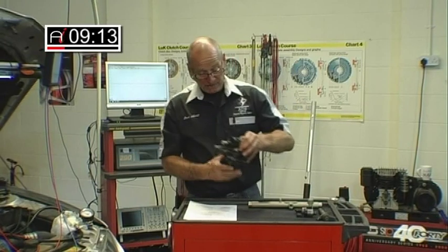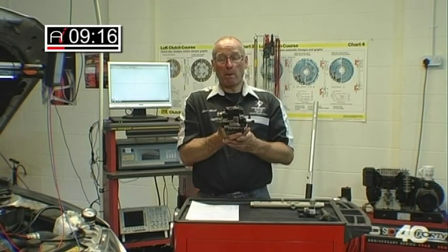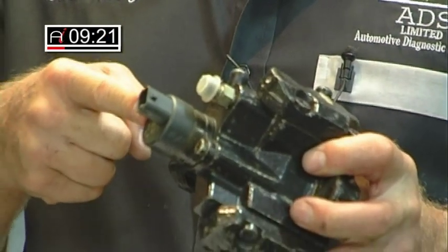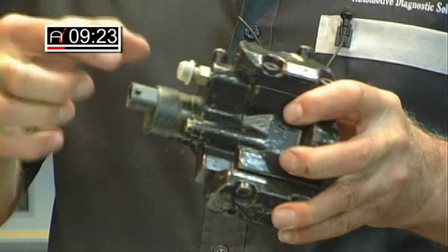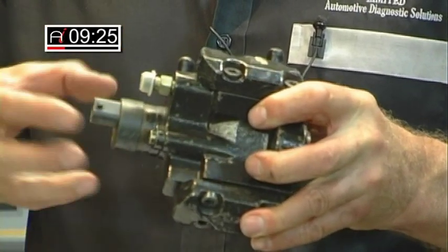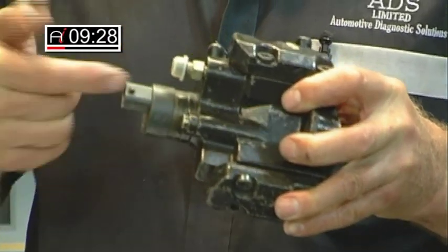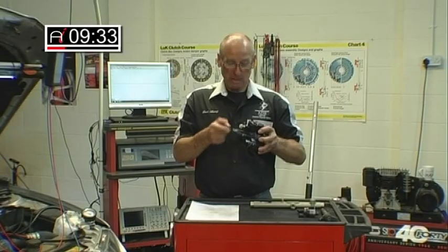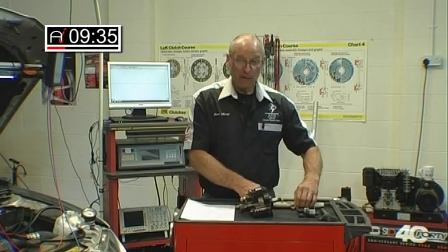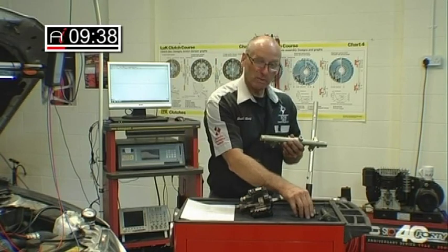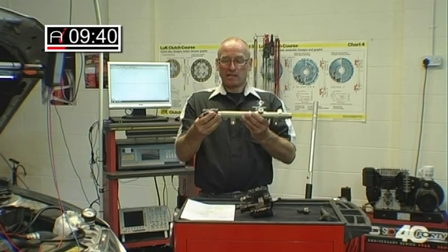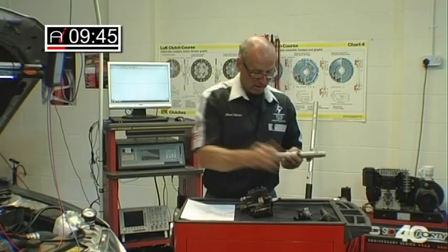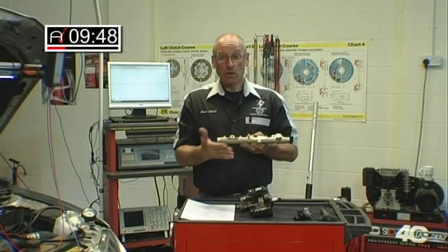The pump on this vehicle is a Bosch CP1, three-piston pump with the DRV mounted on the back of the pump. So the actual escape route back to the tank is controlled by the DRV directly mounted on the pump. In some cases, that device is on the back of the fuel rail or the accumulator. So potentially it could be mounted in that type of position, not in our case. In our case we have a blind rail, which is what this one is, with a CP1 pump.